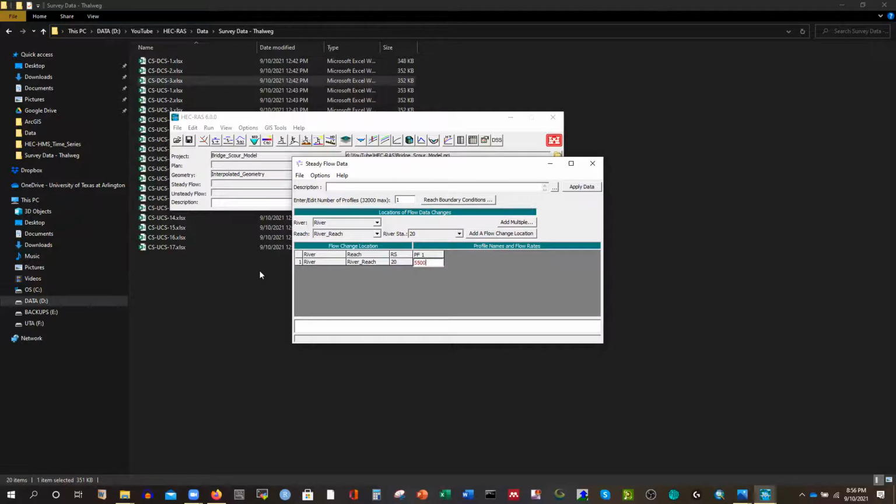If you have two rivers connecting together, or you have different flow rate that is contributing, you have any tributary, distributary, you can add at which section. If you have any tributary of a river at section number 15, you can select that cross section and you can add that one. In the future video, maybe I'll show that, not a problem. But today I'm gonna just show you only one single reach and single simulation. Then I'll add different condition as well, okay.